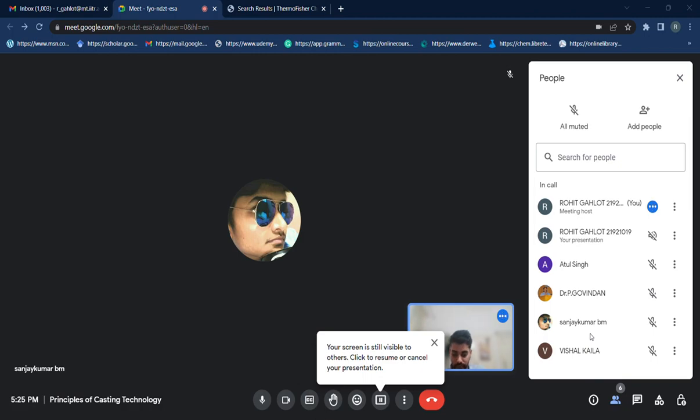The defects are generally that the die life decreases as the melt temperature is high, it is limited to non-ferrous alloys, and the products may have porosity, like air is entrapped sometimes. And the benefits are thin sections with complex shape are possible, precision manufacturing with close dimensional tolerance, true shape of die cavity, casting details are reproduced with high degree of precision, and sound casting, less defective and less cost.